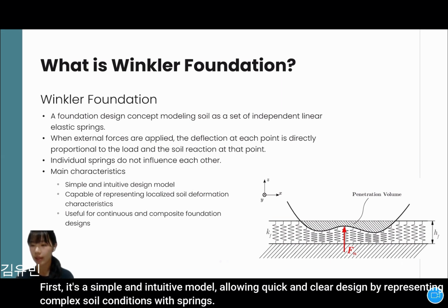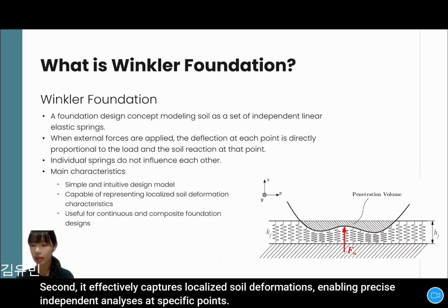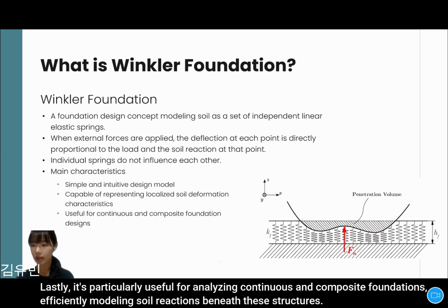First, it's a simple and intuitive model, allowing quick and clear design by representing complex soil conditions with springs. Second, it effectively captures localized soil deformations, enabling precise independent analysis at specific points. Lastly, it's particularly useful for analyzing continuous and composite foundations, efficiently modeling soil reactions beneath these structures.